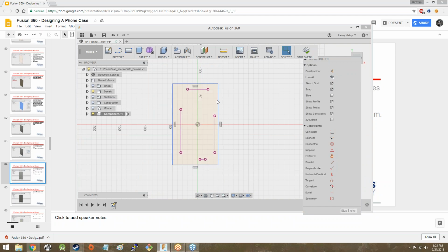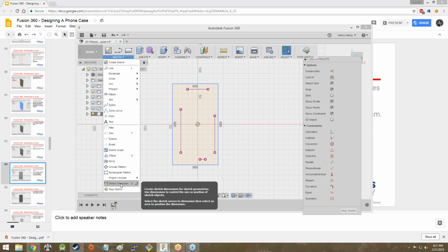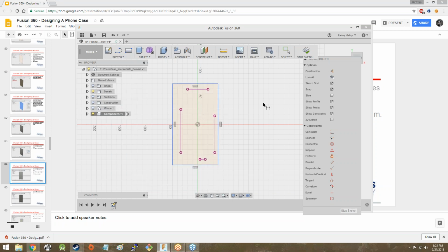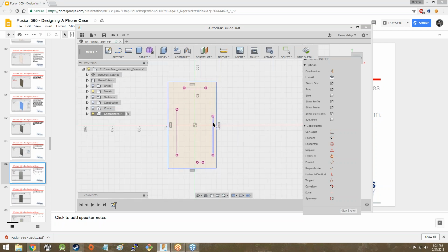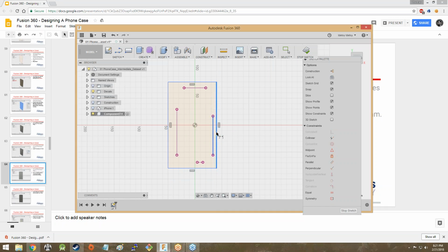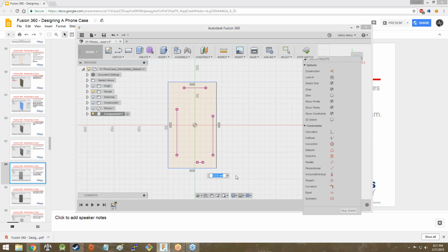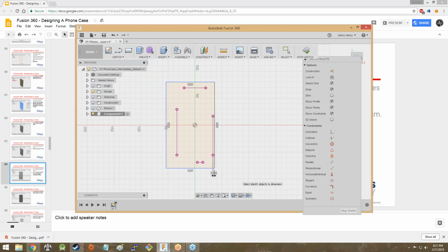So we've got our 4 lines and we've got our rectangle. Now what I'm going to do is I'm going to hit Sketch Dimension. You can also press D on your keyboard in order to bring it up. And then the cursor turns into these 2 vertical lines with the arrows between them. And I'm going to start sketching the distance between these purple lines and their corresponding rectangle edge. So I'm going to select this one and this rectangle edge, and I'm going to bring it downwards. And as you can see, it's 6.515 millimeters. I'm going to change it to 3 millimeters. Cool.